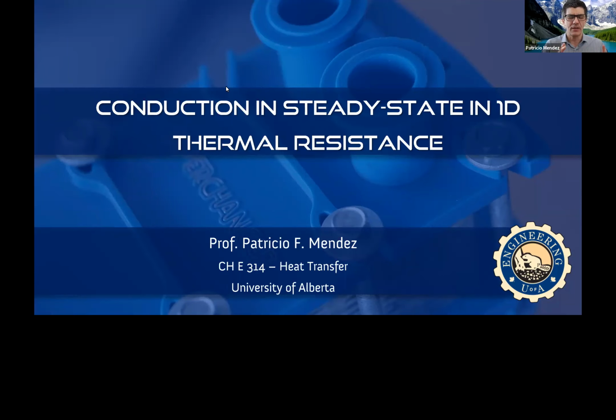In week 4, we said, okay, in lumped capacitance we assume there are no thermal gradients in space. What happens if there are gradients? If there are gradients, we have to make our control volume very small in the direction of the gradient, such that we can make a lumped capacitance consideration for each differential control volume. When we do that, we end up with an equation that depends not only on time, like lumped capacitance, but now also on space. And we did many derivations for 1D.